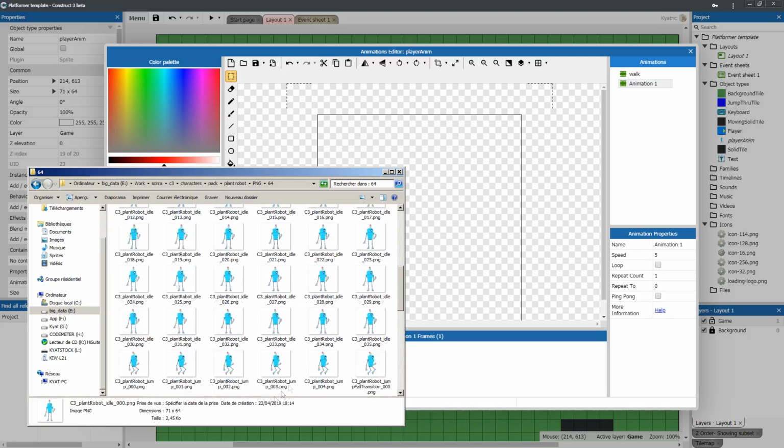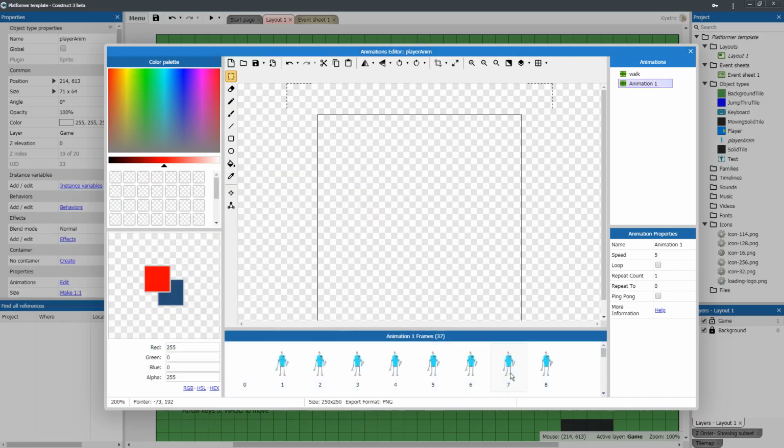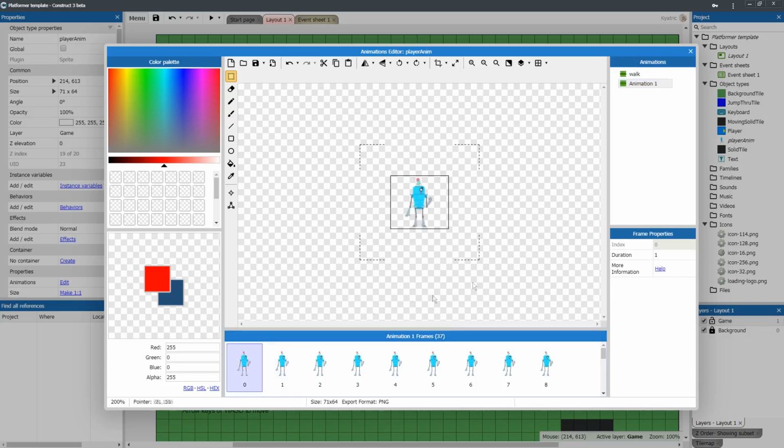Select the frames, this one goes up to 35, shift key, and since it's from the Windows Explorer, I hold down my left mouse button, drag the animation frames, and drop them within the animation frames panel. Again, the first frame I select and delete, and modify the animation's properties. Idle, 24, and this one is going to loop as well.